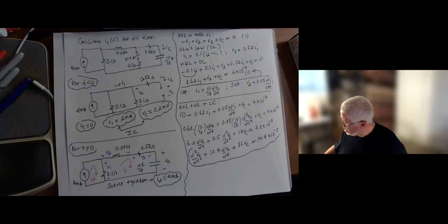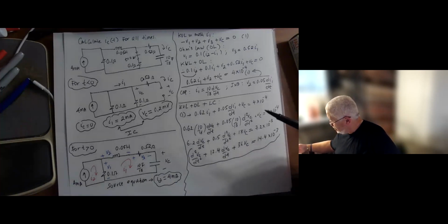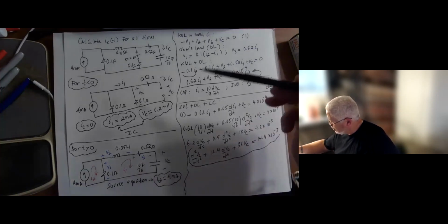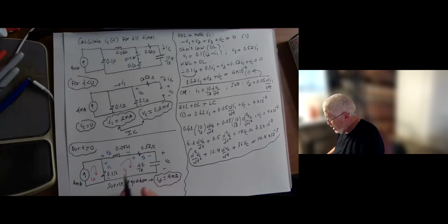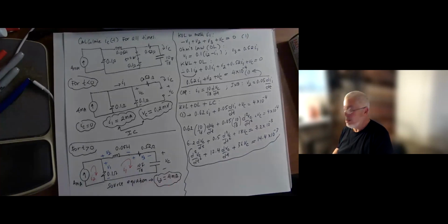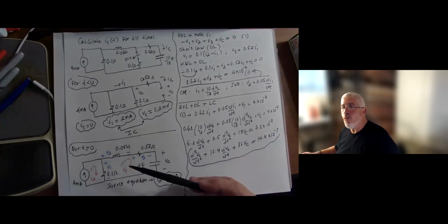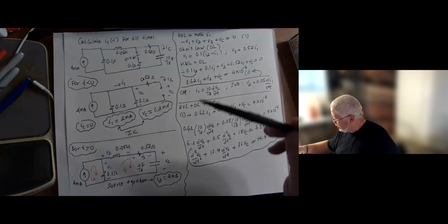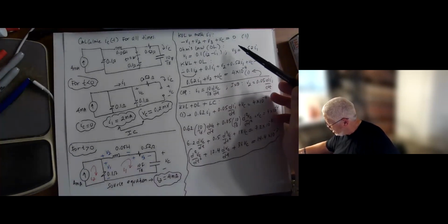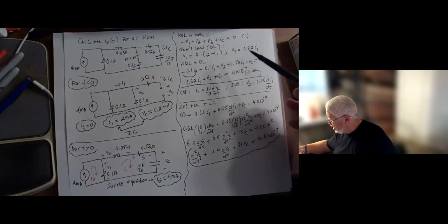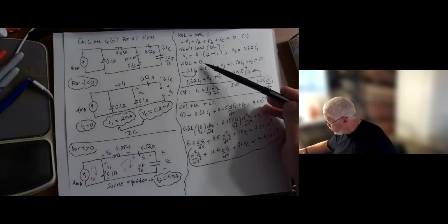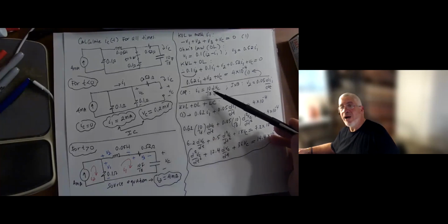So you've seen essentially how I come across this, the standard process here. Once I get the second time period, the inductor and the capacitor are back, I essentially begin a normal mesh analysis approach, source equation, then I go KVL in the mesh that don't have current sources. And then Ohm's law, bring in the Ohm's law, that's the step, KVL plus Ohm's law. Then I write the capacitor. I want to write them separately.